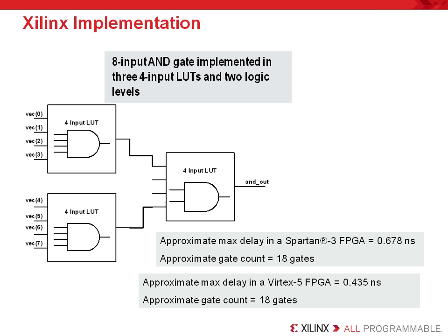You should also note that in this example, the FPGA did end up using a few more gates. That is pretty typical and is not a problem, unless the designer is building a lot of 2-input LUT functions, and generally synthesis tools are smart enough to avoid this kind of situation. The key lesson is that you're not using all the inputs to each LUT. You're going to waste some gates. But if you build with good HDL coding styles, you will improve your design's efficiency and speed.